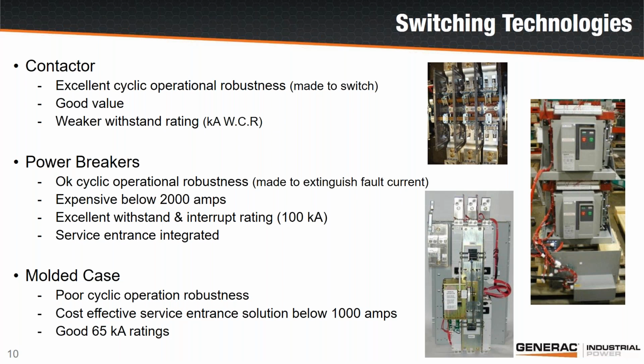But from a general pecking order, I would put the technologies in the order they're listed on the page. Contactor is most preferred. Then for big switches, maybe power breakers, and then molded case is more of a value leader switch for service entrance applications.